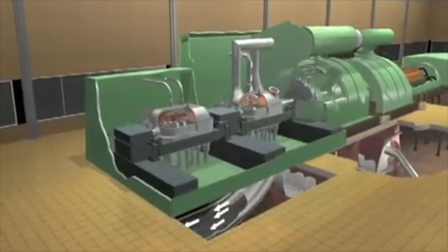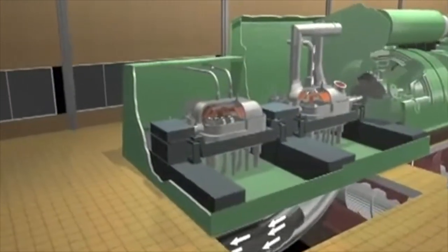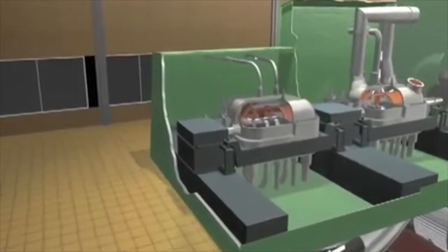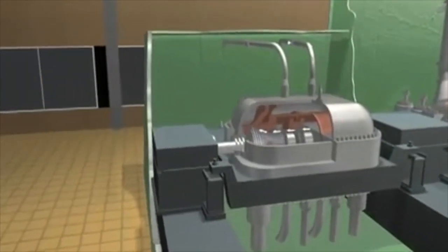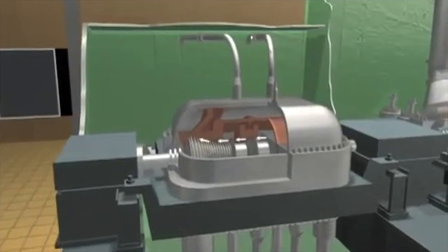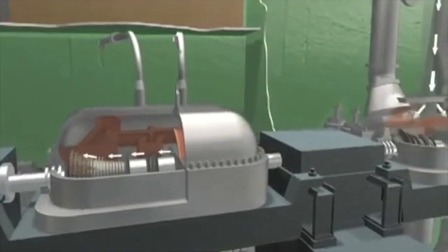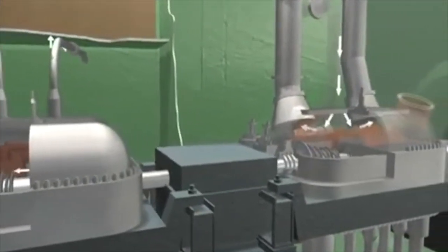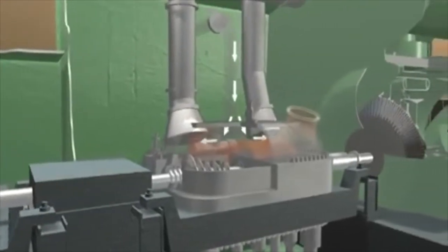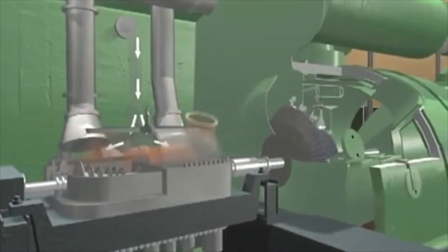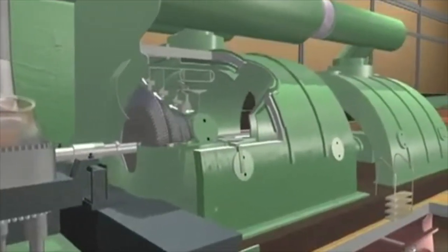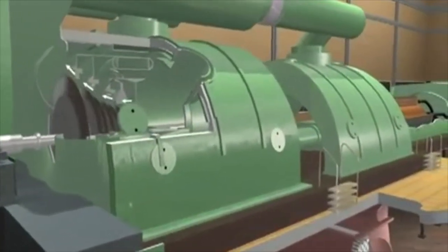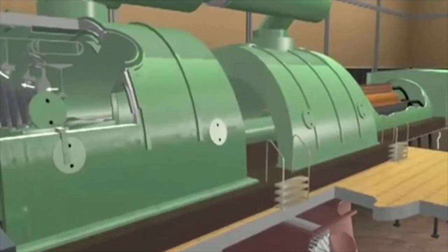High-pressure steam, now 1,000 degrees Fahrenheit at 3,500 pounds per square inch, is piped from the boiler to the first in a series of turbines. Here it expands between layers of turbine blades mounted on the turbine shaft. The steam loops back to the furnace, then onto the second turbine. In this process, the steam turns the series of turbines 3,600 revolutions per minute, providing power to the generator, the last in the series of machines.